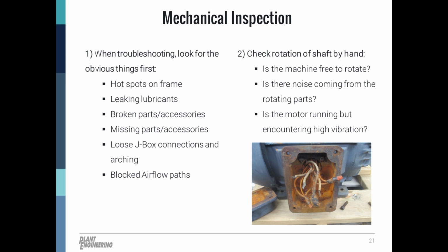So, we would look for leaking lubricants under and around the motor. Leaking lubricants can play a big role in understanding if the motor bearing grease is getting too hot, or if the motor bearings are not getting enough lubricant.